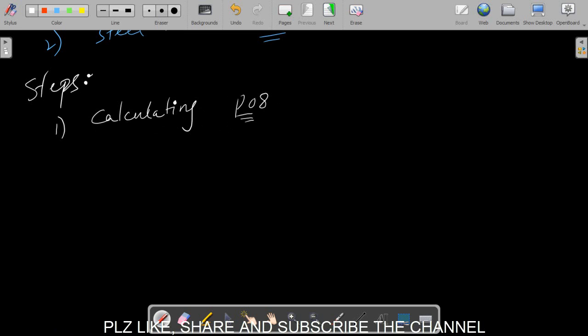So we have a plan of the building, and from that plan we assume different types of live loads. We calculate the building component loads by using their densities, and then finally we get the load in units of kilonewton per meter or kip per running foot.